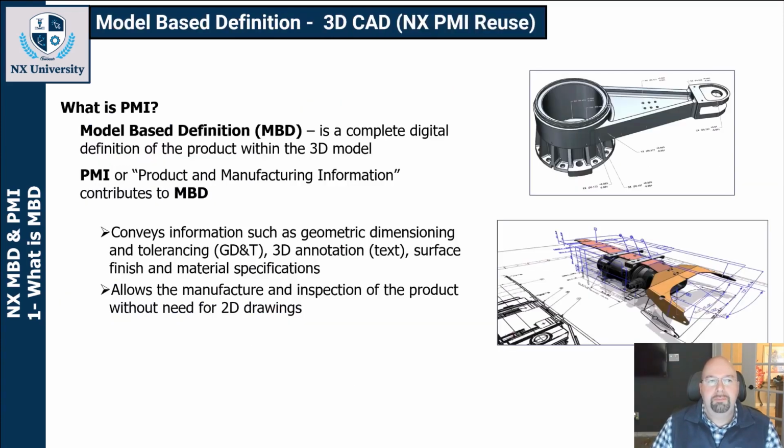Getting into what is PMI here, a model-based definition is the complete digital definition of that product within your 3D model. That PMI is the actual product and manufacturing information, things such as your dimensions, GD&T applied to the part, different areas that you can mark off on the part, security markings. So this is going to convey information such as geometric dimensioning and tolerancing, those 3D annotations, surface finishes, and material specifications on the part. This is going to allow for the manufacture and inspection of the product without the need for those 2D drawings.